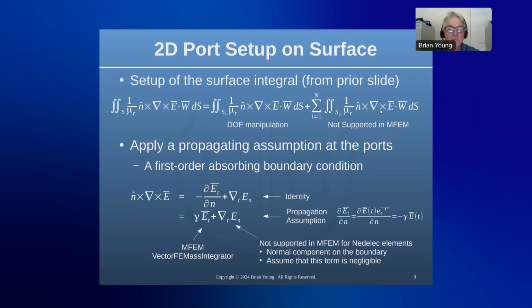Where I am at this point was to get something running up to what I would consider minimal commercial quality, which is something that runs very well with a regression suite backing it up and a lot of examples. As an example, for the last week I've been running the regression suite in a loop. It takes an hour and a half to run the 3D regression suite, and I set it up to run 40 times looking for anything that would pop up. And actually, something did pop up. I fixed it now, but the preconditioner in PETSc fails about 0.8% of the time.